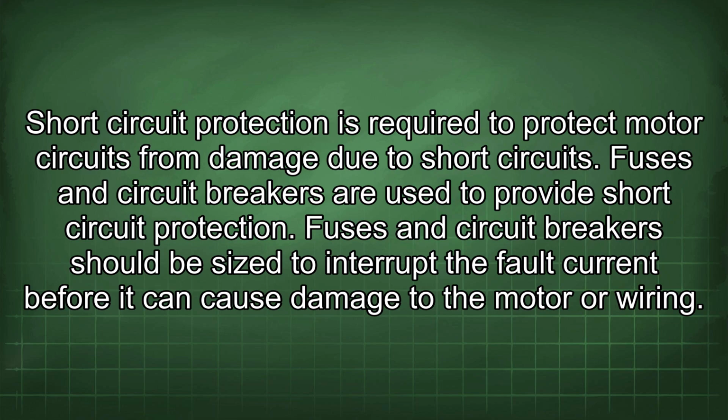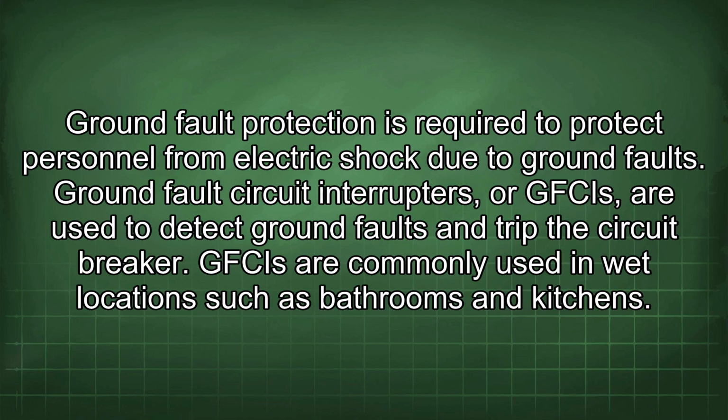Short circuit protection is required to protect motor circuits from damage due to short circuits. Fuses and circuit breakers are used to provide short circuit protection. Fuses and circuit breakers should be sized to interrupt the fault current before it can cause damage to the motor or wiring. Ground fault protection is required to protect personnel from electric shock due to ground faults.